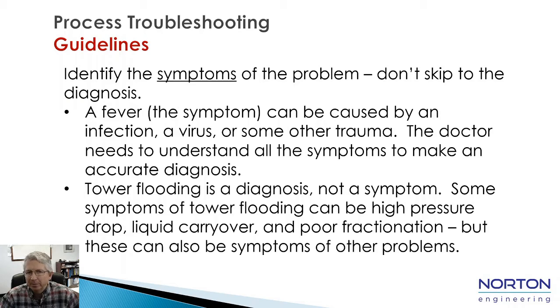Tower flooding, for example, is a diagnosis, not a symptom. There may be symptoms of tower flooding that can be things like high pressure drop, liquid carryover, and poor fractionation, but these can also be symptoms of other problems, so it's important to understand what all of the symptoms are associated with the issue before you jump to the diagnosis.